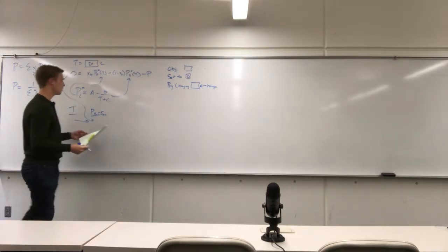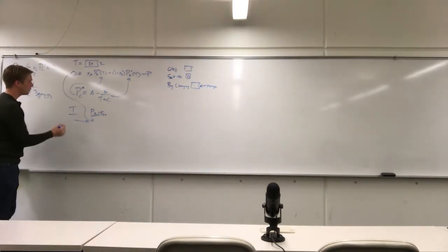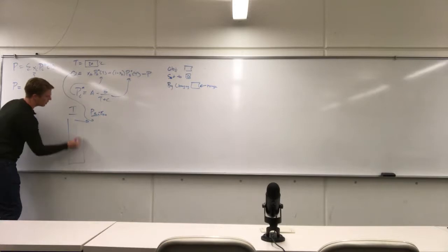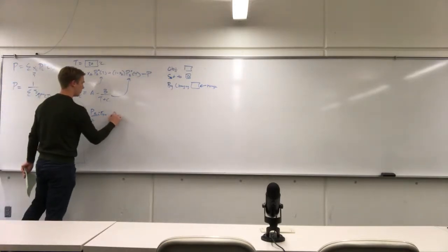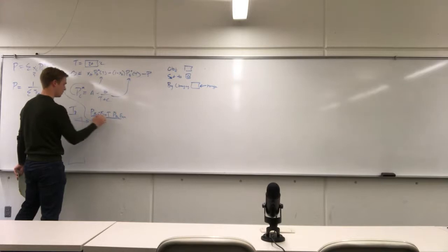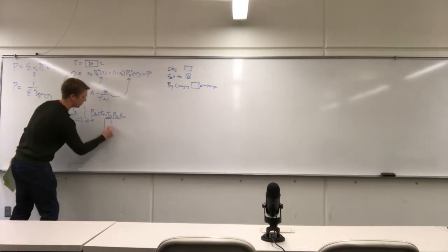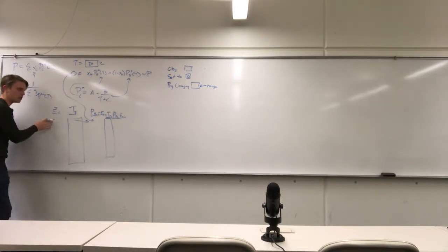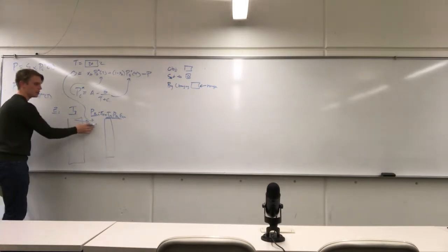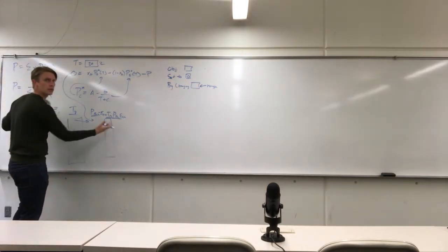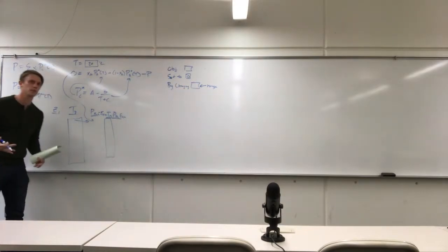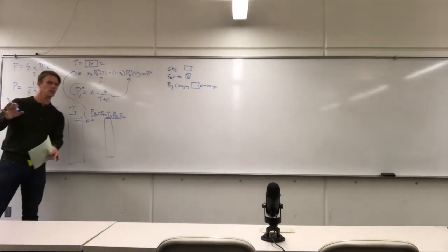But in this case here, what you'd want to do is change all of the temperatures. So rather here you have Z of i, P bubble, P dew equation. And you'd actually have another one, T here. So this is T bubble, this is T dew. So you'll have to do this twice. So you have your Z, you change your P bubble, satisfy this equation, change your T, satisfy this equation. That's your bubble temperature, dew temperature. Does that make sense? Mm-hmm.